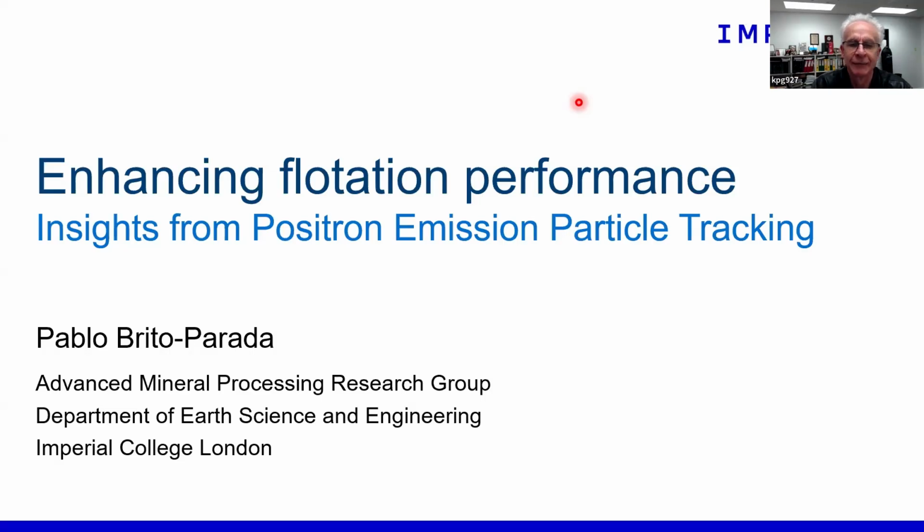Really enjoyed that. And yes, I think first time I heard about some of this work, we were also working on the Corsair, and one of the interesting conclusions that we reached was that, particularly in relatively small diameter units, there is a wall effect that relates to the ability of the gas bubbles to uniformly engage particles near the wall that are in the fluidized bed. And I think this is a brilliant technique to tease out those sorts of nuances.